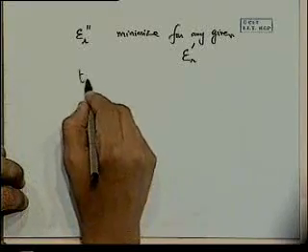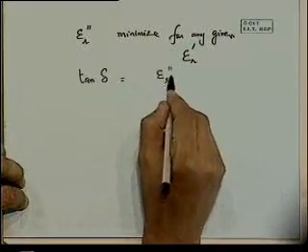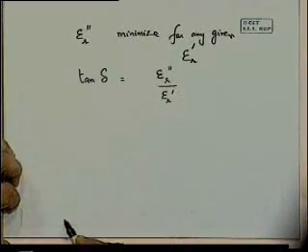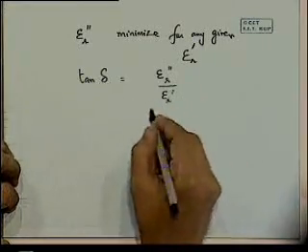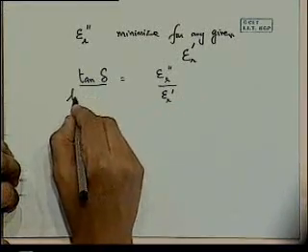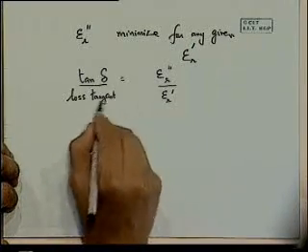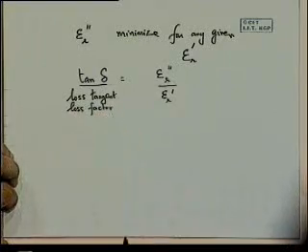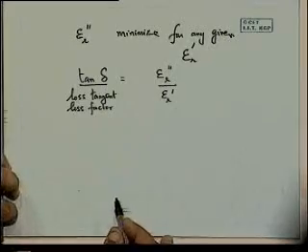And so a quantity is defined called tan delta, which is epsilon r double dash by epsilon r dash: the loss, the imaginary part, by the real part. Tan delta is known as the loss tangent or the loss factor. And the smaller it is, the lower are the losses.